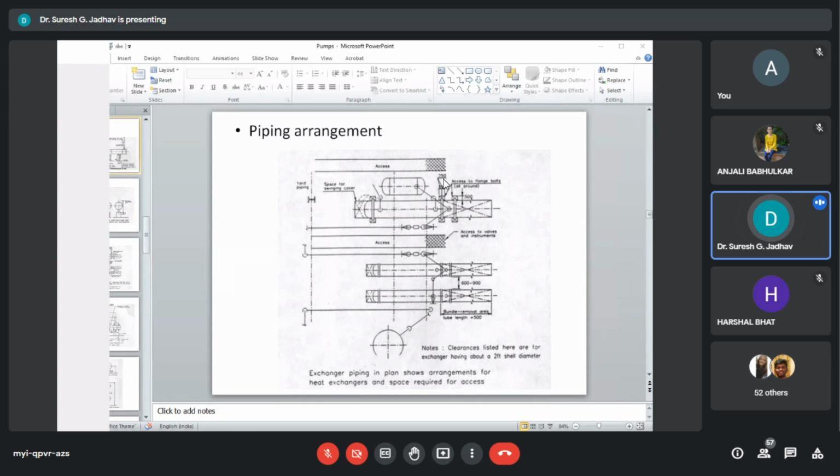The cost increase in modification can be more than offset by the cost effective piping. This factor influences the decision on piping routing as well. Elbow nozzles permit lowering of the heat exchanger to grade, with better accessibility to valves and instruments. For this purpose, we have to consider the piping arrangements.